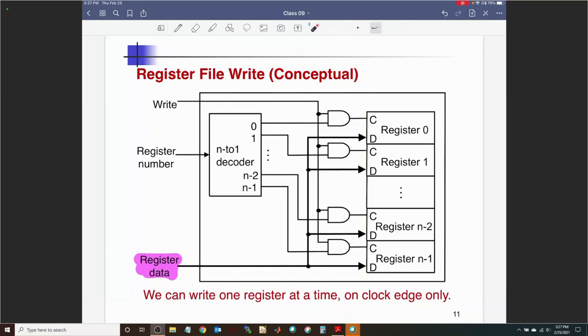That is going to be 32-bit, right? This is 32-bit. But it can go here to this guy, to this guy, to this. The data can go into any one of the 32 registers. The wiring provides us with that option. However, you have a register number that is going to activate one and inactivate all the others, right? So that's your decoder, right? It has one active output at any given time. That's your decoder, and it'll take the responsibility of having only one output active at any given time.